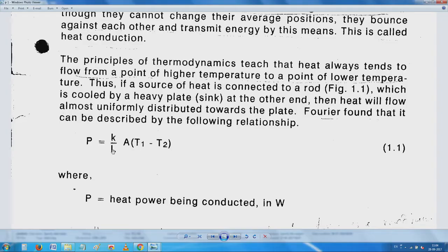He will give you exactly the dimension of the conduction plate that is attached to the transistor. Usually there is no issue about it. Usually at the surface, we are not so much interested in whether it is aluminum, copper, or some other material, but we are interested in the area. The more the contact area, obviously more power can go. Easy to understand. Next comes something which is not very intuitive, that is L, big L.